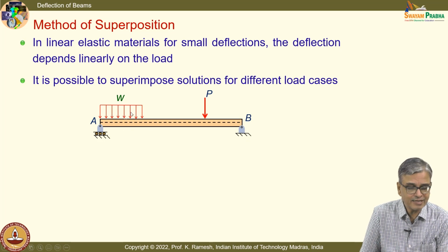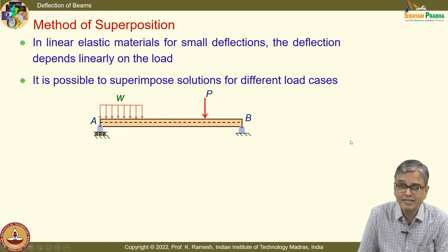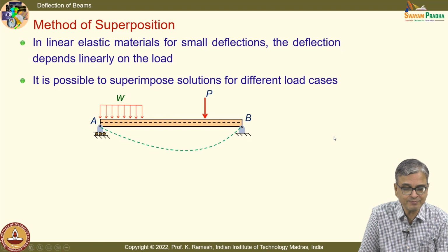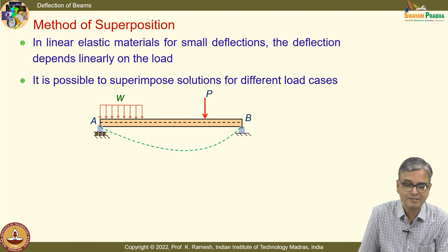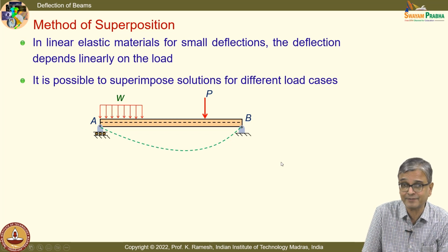And another one is I have a loading which is not symmetric. So, I will have a deflected shape which is also not symmetric. That much amount of recognition you should have. Can I draw the diagram something like this? Because I have a load here, this is pull down here more, fine, and this deflected shape is not symmetric, do not draw it symmetric.